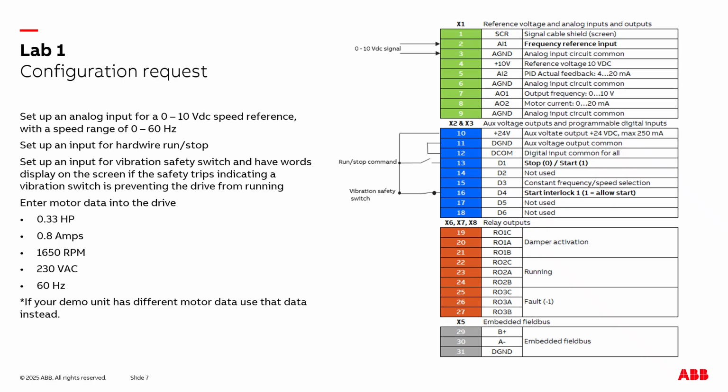And why is that? Because DI1 by default is set up to receive a hardwire run stop command. This again, if you reference back a couple slides, I showed you the default setup for inputs and outputs on this drive, and that makes it easy if you reference that to understand where to land some wiring to make your startup much faster.